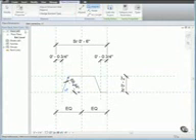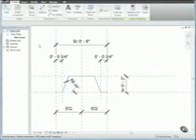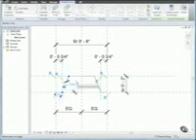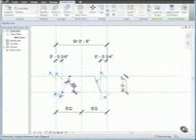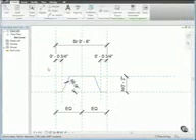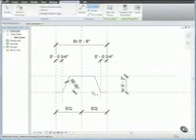Then click Modify. Then select the angled reference plane and click the dimension value and type 66 and press Enter. Then select the angular dimension and click the lock symbol to lock the angle to the horizontal reference plane. Then, using the same method, place an angular dimension on the other side.